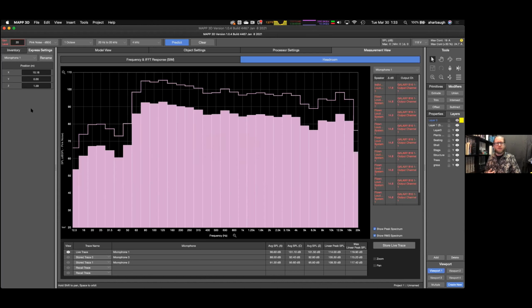And if you're familiar with MAPP XT and how that showed SPL headroom, when we scanned the loudspeakers for MAPP XT, those were at limit. So this is basically going back to MAPP XT's way of showing SPL headroom of the product's full potential of SPL. All righty. So now we can see everything's in the red. We're pushing it all the way we can go and still be linear in our SPL headroom. So I can see from the system at this microphone, I could get 96.6 average SPL with A weighting.